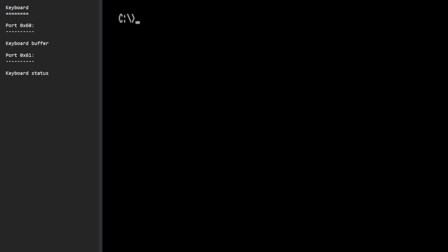And what I think happens here is that as soon as the keyboard is satisfied that it's been dealt with, it lowers the interrupt request, and that reflects immediately in the interrupt request register. I will test it after I finish this video on genuine hardware just to make sure. So it looks like we finally are able to control the keyboard without messing up our cycle accurate timing, and so now we're ready to move on to the next step in trying to get a cycle accurate graphics effect.